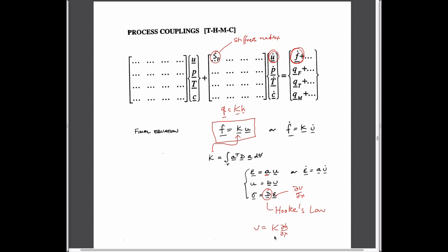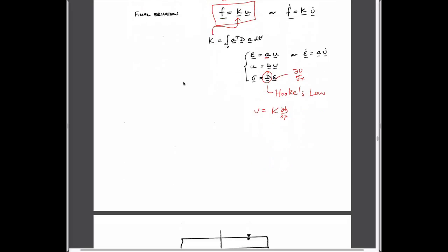And so you remember before, what did we have? I think we called this R22, we called this S22. And we ended up with, these were our flow equations. This is our conductance matrix. This is our storage matrix, which operate not on pressures, but on heads, because we chose to write it in those terms. But it's basically the same thing. And so maybe this puts it in the right context for you.